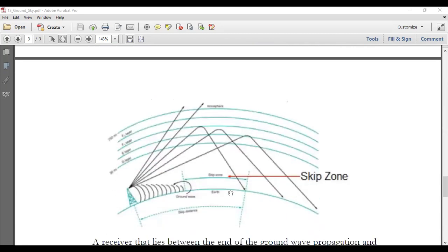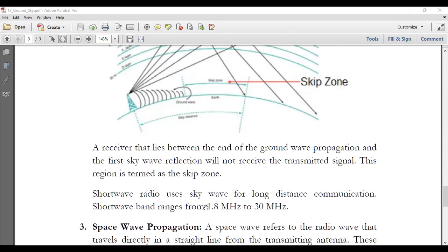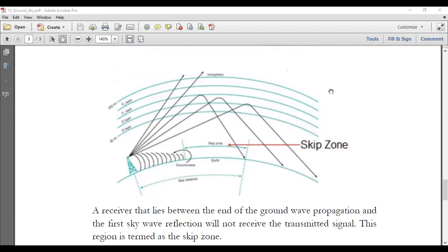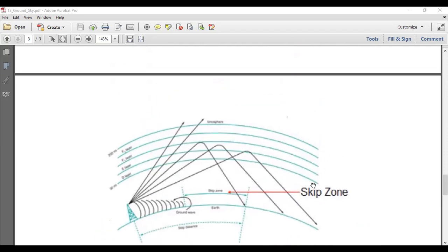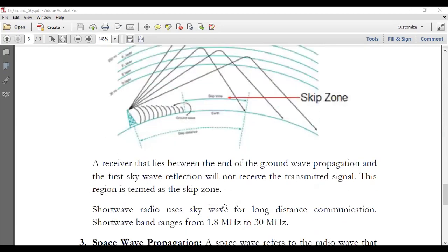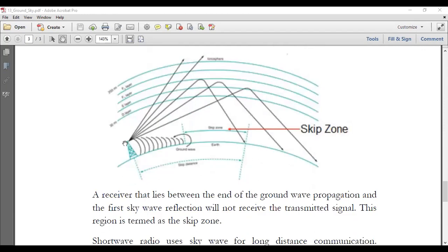So this way you can actually cover a very large range and intercontinental communication is possible. And also it is possible that you have a reflection on the ground, because ground is a good reflector, and you have a second internal reflection. Okay, that becomes very weak though, but it is not impossible. So actually this is called skywave. This way you cover a large area.